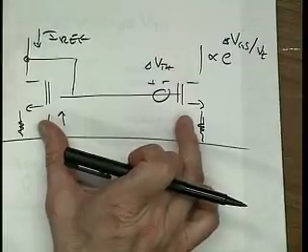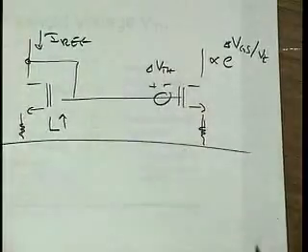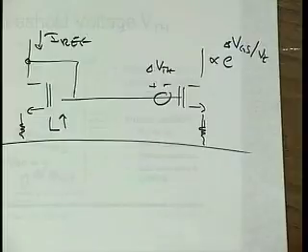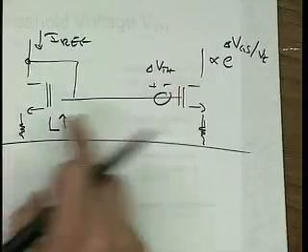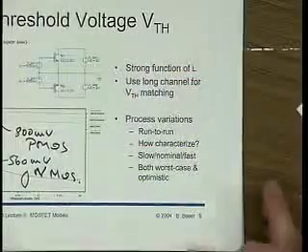So most of the time we use a current mirror or a diff pair or so, and then the absolute value of the threshold voltage isn't that important, as long as it's not larger than the supply or a substantial fraction of the supply. So it's inconvenient, right? It's just got to be equal. So how do we make it equal? Well, we make devices that are certainly both the same length and they're close together. But there is one more thing.